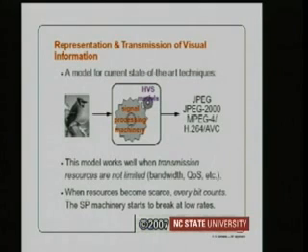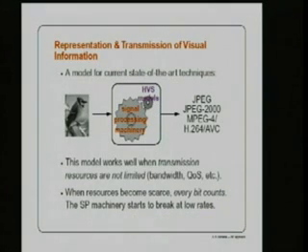We have excellent statistical models for these signals, at least from a completely signal-based standpoint. We have a lot of good, very effective frequency-based techniques for dealing with them. We know how to quantize them. We have very sophisticated entropy models. And we put a very, very little bit of human visual system modeling into the big box that has the machinery. I think everybody's familiar with JPEG at this point, right? JPEG 2000 has a lot of improvements on the signal processing machinery. MPEG 4, H.264, advanced video coding, pretty much any video or image compression technique fits this mold.